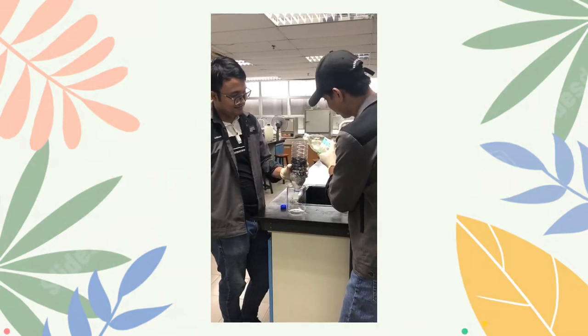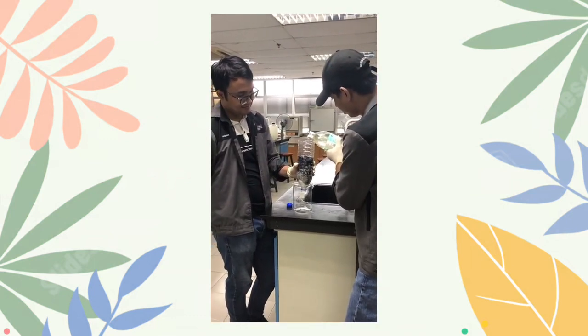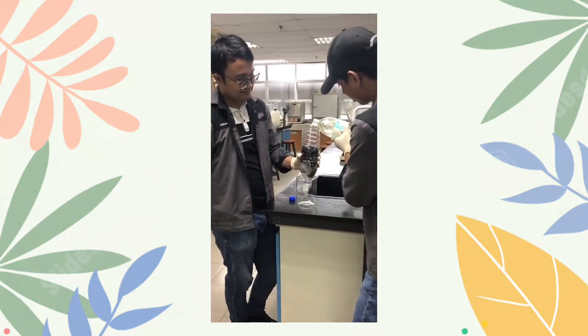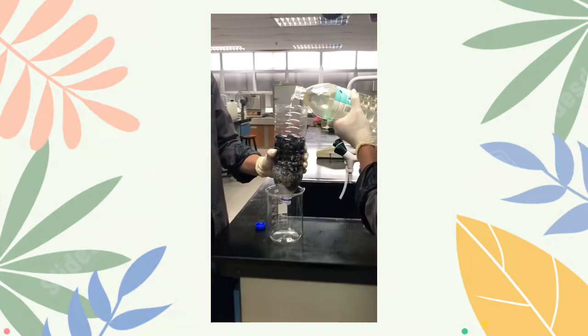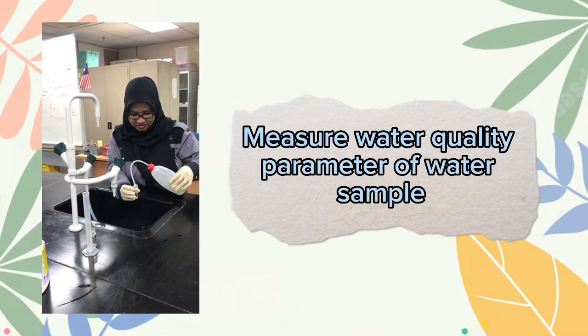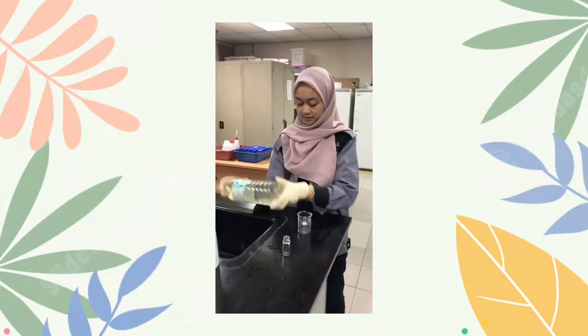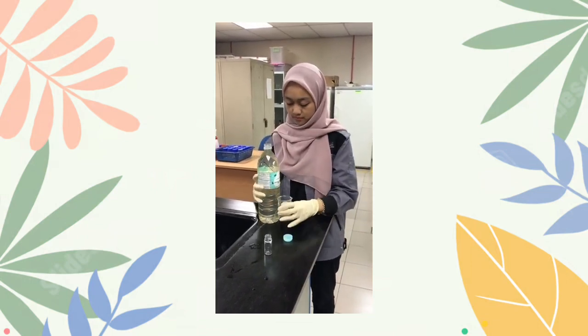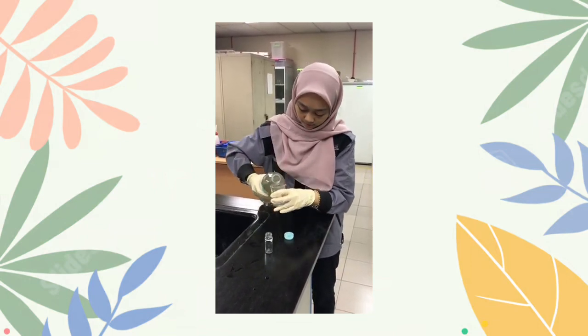Put the water sample into the water filter. Gravel filters out larger sediment. Cotton filters out fine impurities. Charcoal removes contaminants. Wash the turbidity bottle with distilled water. Shake the water sample and pour it into a small beaker, then transfer it into a turbidity bottle.